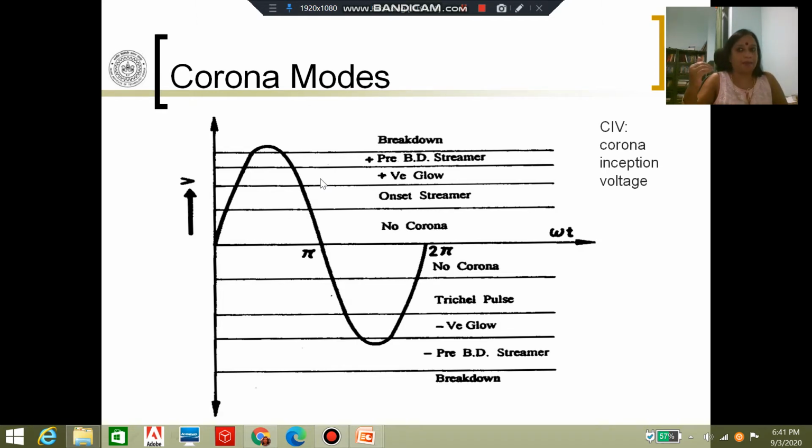So essentially there are some discharges, very similar to what we discussed in the streamer mechanism. These discharges cause ionization of the air further and further away from the conductor surface, and these streamers are redistributing charge in a bigger region around the conductor surface. And obviously, if you increase the voltage further, breakdown happens. This is to be distinguished from corona or partial discharge. Breakdown means there is a continuous conducting path between the high voltage and the low voltage conductor. That means now there is a line to ground fault.